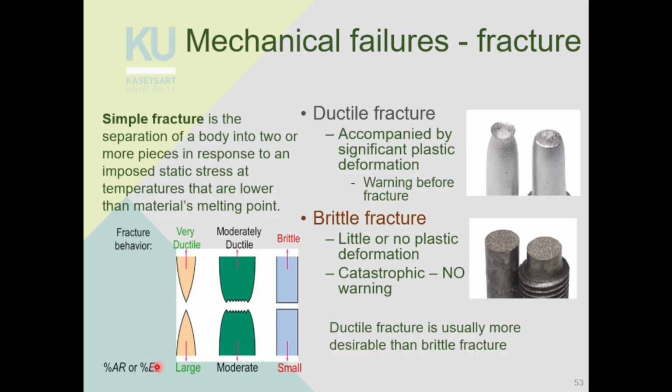Okay, percent elongation is basically percent strain, right? So for brittle material, that means when you're applying tensile stress, it doesn't stretch too much, right? It breaks quite easily without getting a lot of strain. Okay, so it is quite brittle. You have a small amount of elongation, and the other type of materials are ductile materials. When you have large percent elongation or large percent strain, it will be stretched quite a lot before it breaks.